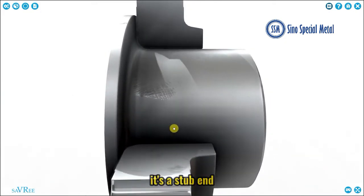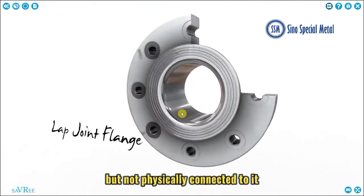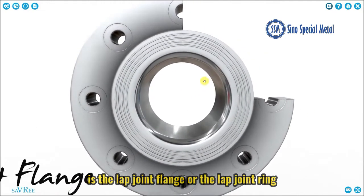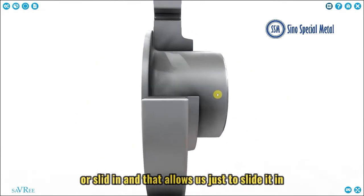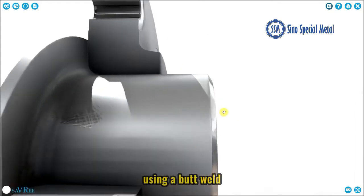It's a stub end. Around the stub end, but not physically connected to it, is the lap joint flange or the lap joint ring. So this entire middle piece can be slid out of the lap joint ring or the lap joint flange, or slid in, and that allows us just to slide it in and then connect it to the end of a pipe using a butt weld.